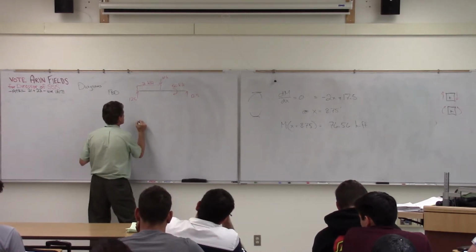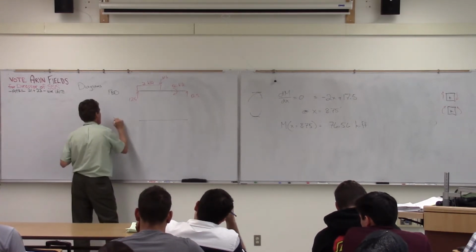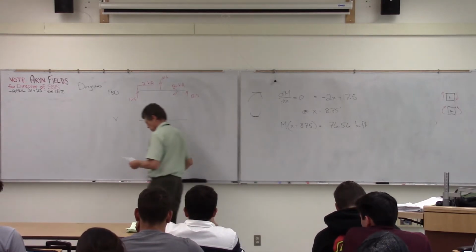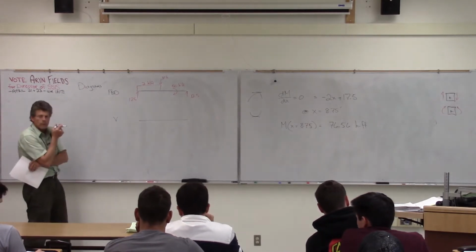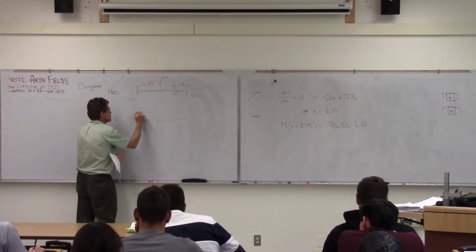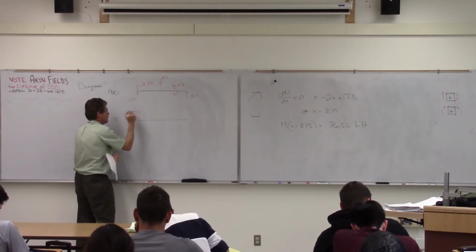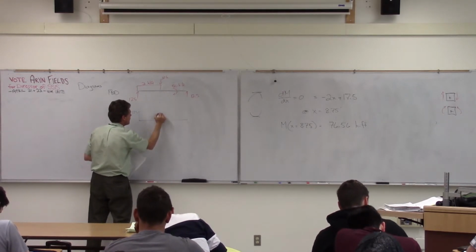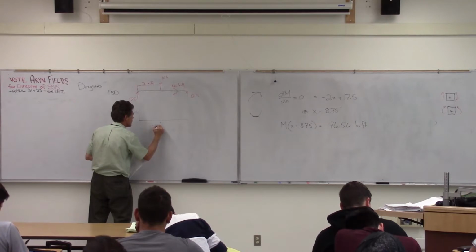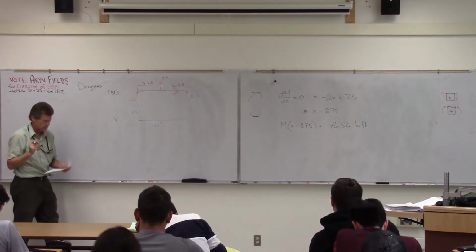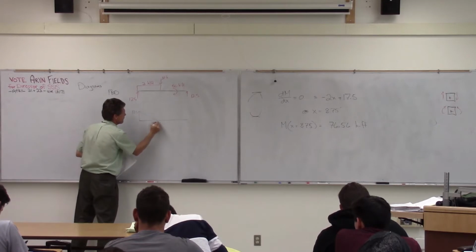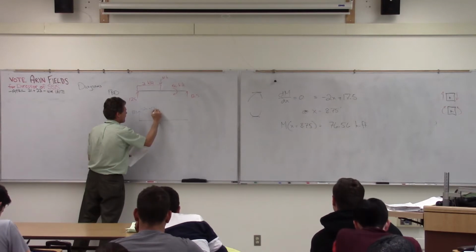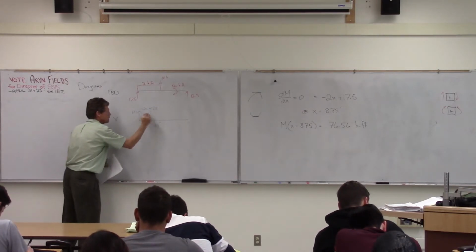So the next piece we'll draw is our shear diagram. And we'll choose another cool color here. We'll do it in blue. Okay, so we talked about it. Our starting point was 17.5, right? And by the time it reaches that 10 there, it draws down to minus 2.5. And then I've got my equation that says it's linear. So I just simply plug that in, draw it.